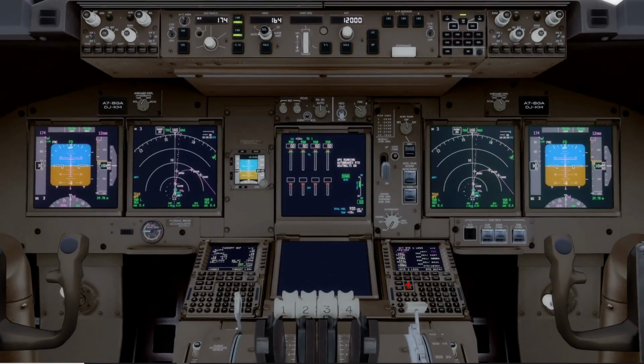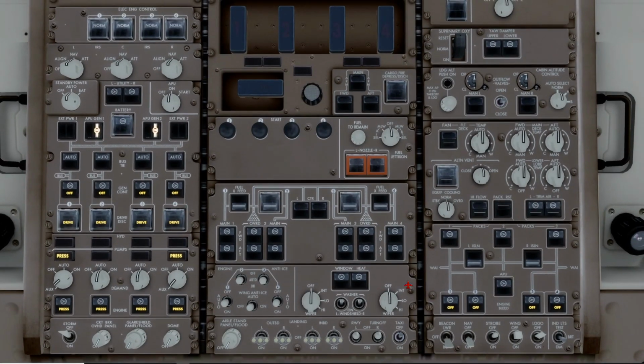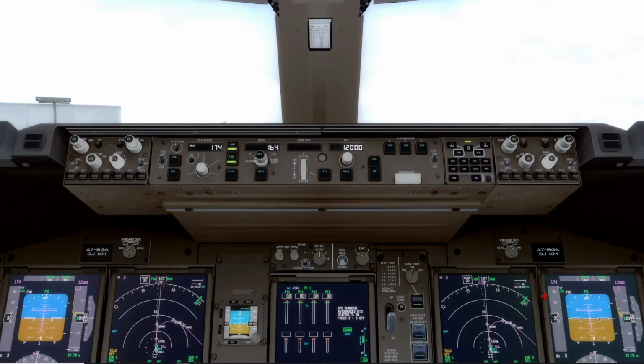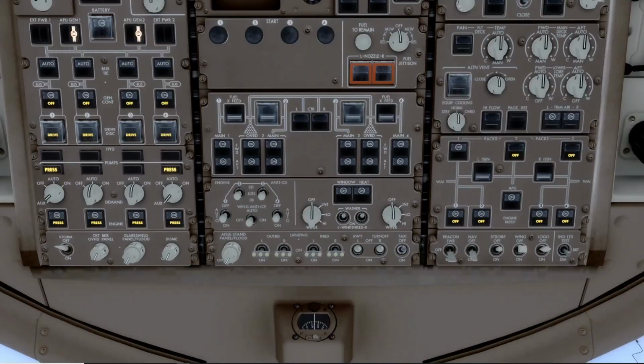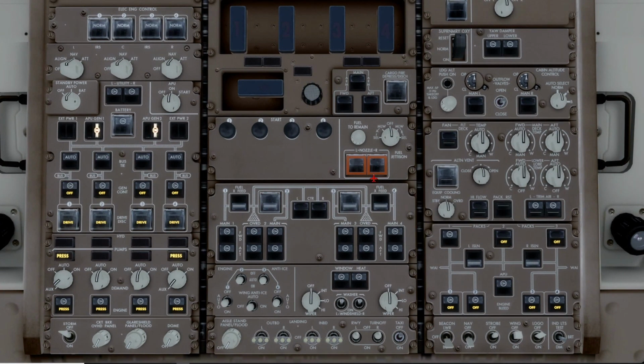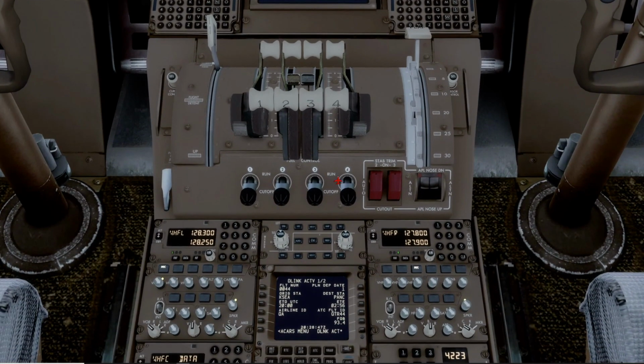And so then we could go up to the FO would come up here, turn 2 or 3 packs off. We'll turn 2 off. And then I'd say start 4 and 3. And then he'd reach up and say starting 4 and 3. And then I'd come down to the fuel control switch and bring 4 and 3 to run.